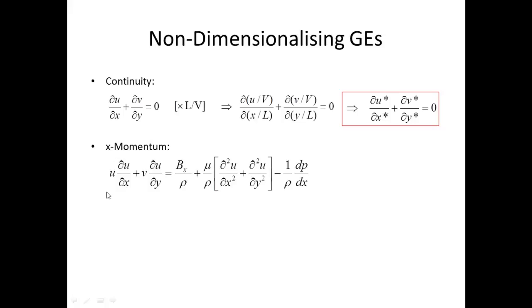The x momentum equation for a two-dimensional flow with a body force Bx is shown here for an incompressible fluid. This is the Navier-Stokes equation for the x momentum. Also, the assumption that we have discussed earlier was that the body force is 0, and as we have seen earlier, the gradients in the x direction can be neglected. So dou square u by dou x square becomes 0.